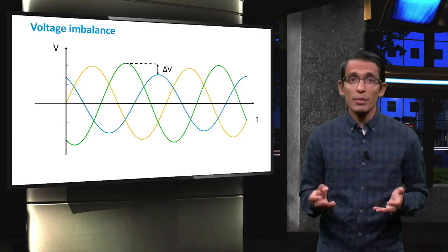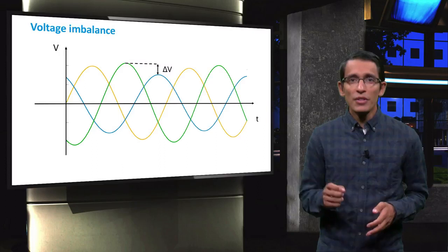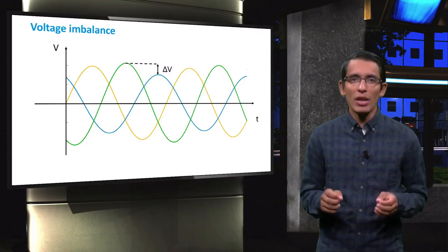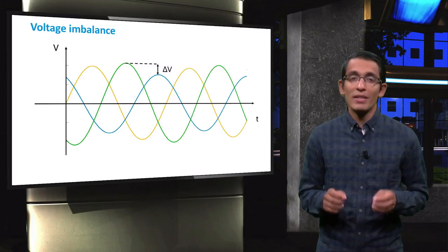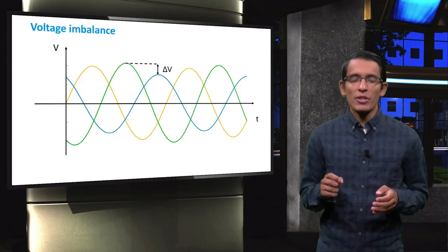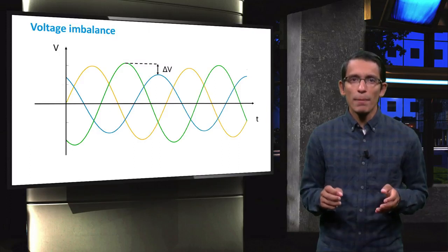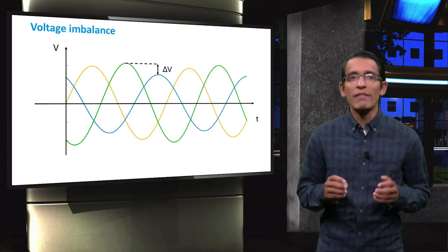Damages to control systems and damages to transformers can also occur. This is the reason why at high PV penetrations, the cumulative size of all systems connected to each phase should be as equal as possible. Generally, all systems with installed power above 5 kilowatt peak should be connected to an inverter which can guarantee a balanced three-phase output.